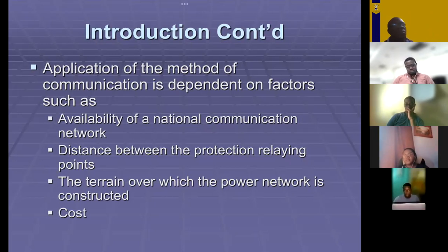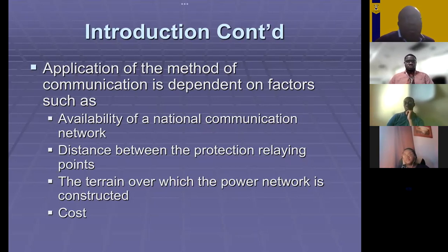So one has to think about how much they were paying all these people to maintain the equipment. They were basically replicating a communications company. So you go to a substation and you pick up the phone and call the other substation, it wouldn't be costing you anything. But at the same time, what's the point in maintaining all these multiplexers and demultiplexers and antenna and all of that? Yes, simply for your protection system.